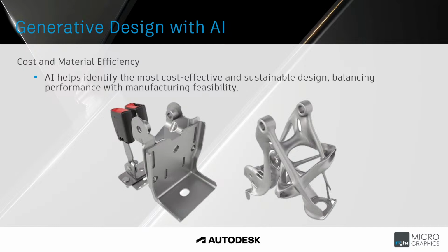So that generative design has those built-in functionality to choose your manufacturing process, the materials required, and this can help you reduce, let's say, material wastage or choose the correct or available manufacturing processes that you have. Let's say you can only 3-axis machine, so you would choose that and create your outcomes according to the 3-axis machining. So that is a quick overview of generative design with AI from a structural perspective.